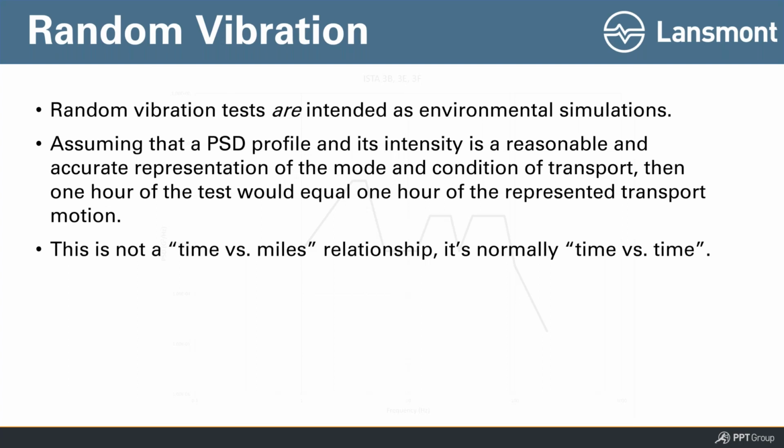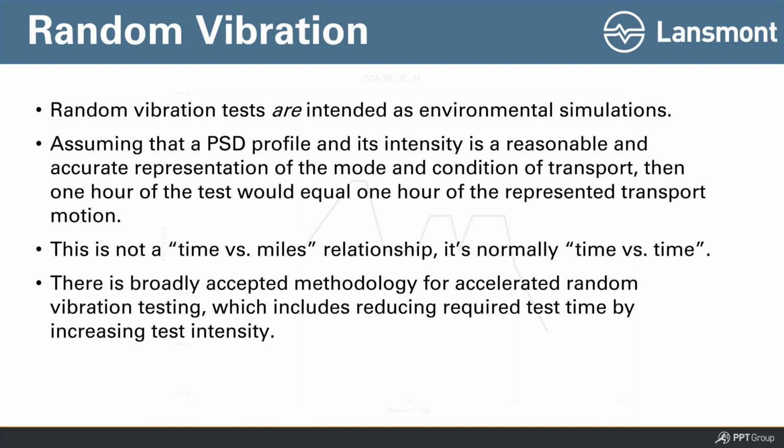Well, in the absolute definition of things, if you go out and you measure 1 hour of vibration and you create a PSD, a power spectral density profile, based upon that 1 hour of measurement, that 1 hour equals 1 hour of test time. That's what you would use to simulate that environment. It's not 1 hour of testing equals 500 miles, or 1 hour of testing equals 1,000 miles. It's time per time, basically, when you measure data.